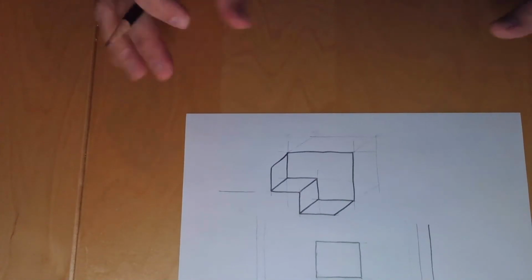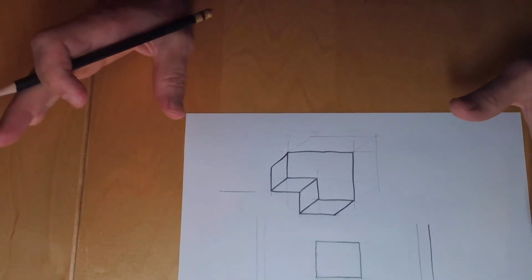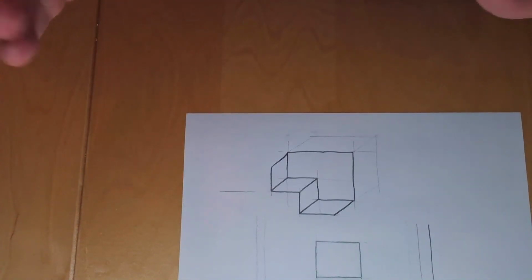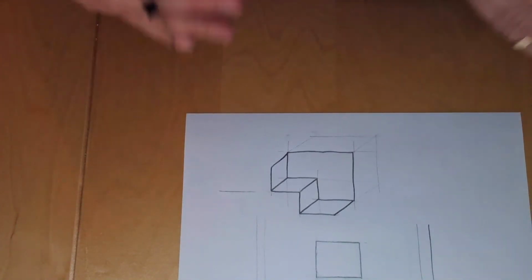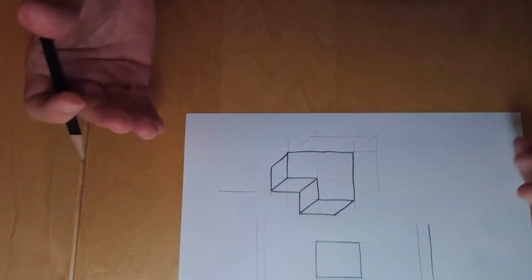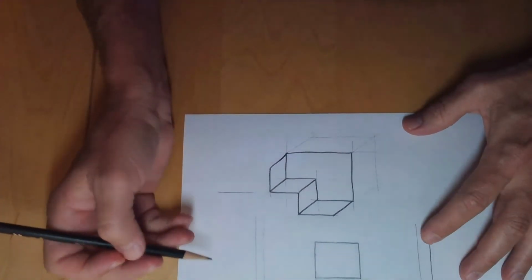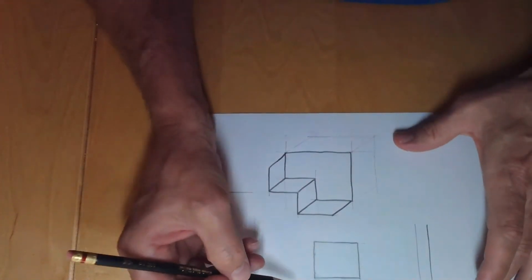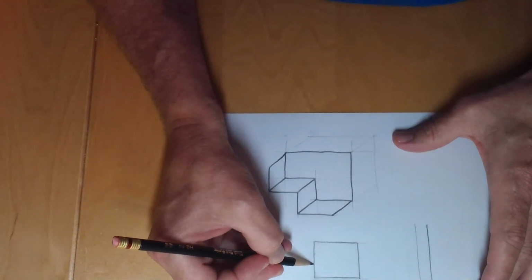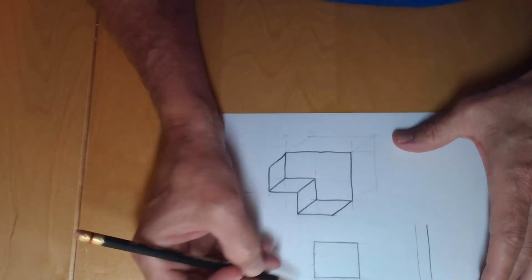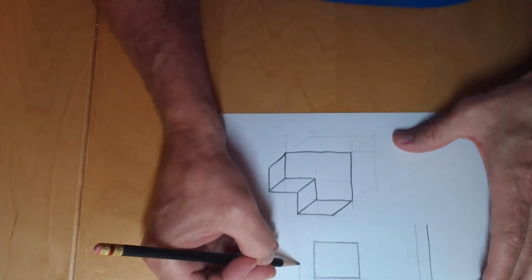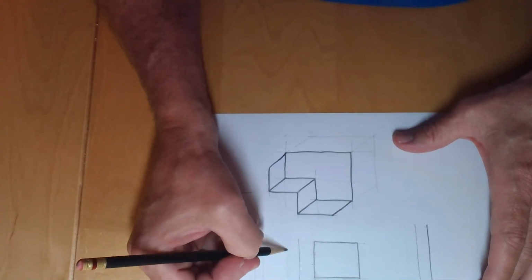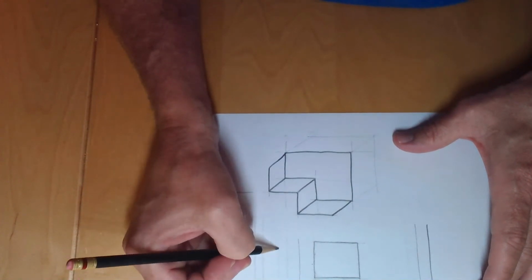So sketching is very simple, but it's something that we can focus on and get better and better at. I want to keep it simple for you, so I want you to focus on really 3 different line weights: solid, dark, thick; a thin line weight, which I didn't do in any of these examples; and then the barest whiff of a construction line weight.